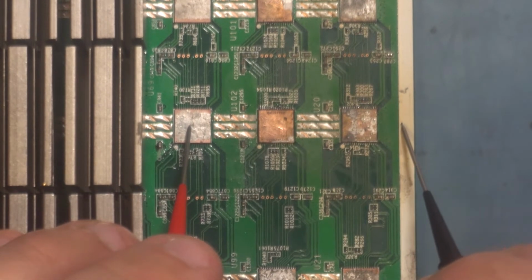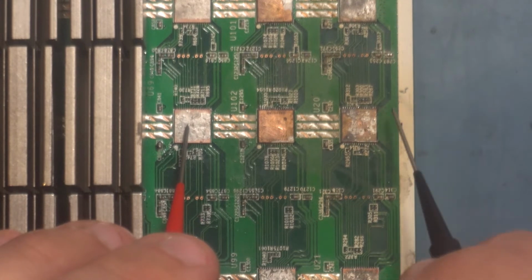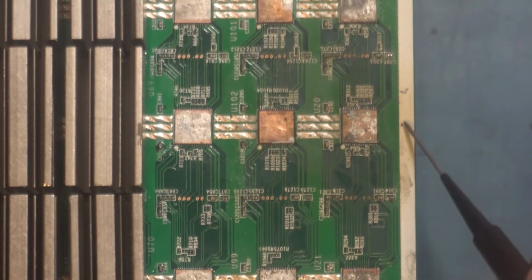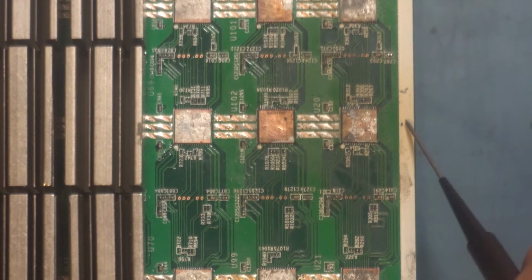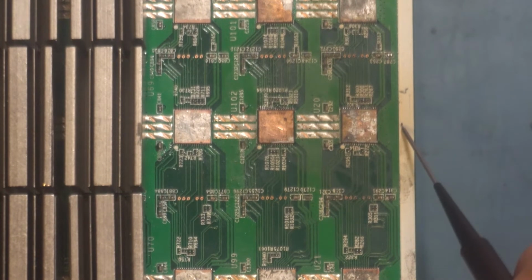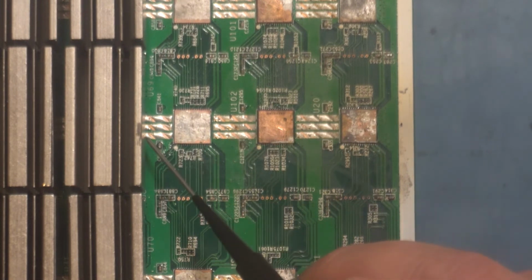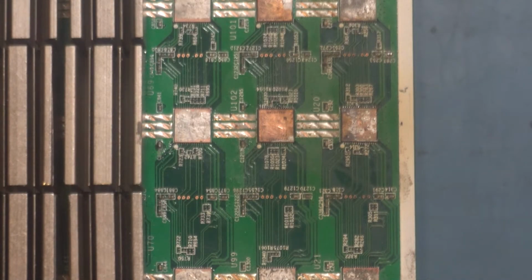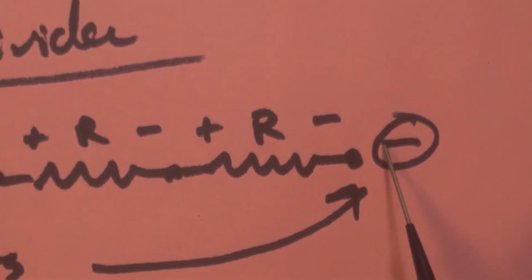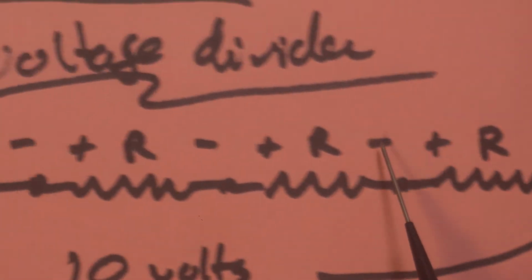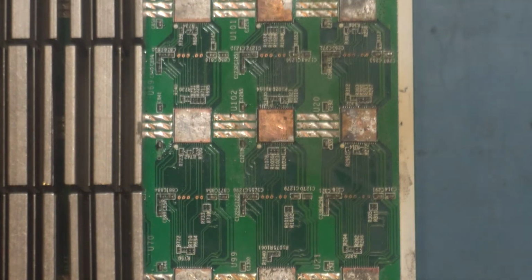So on this side, this is domain number 1, this is the start of the series chain that's going that way. So this is the most negative part that's directly connected to my main board negative post. And then as far as voltage, it just keeps getting higher and higher as I move up, much like from here, it was getting higher and higher as I was moving this way, right? So starting from 0, the main negative, all the way to the main positive of the board, which is let's say 24 volts for an S17 Plus.